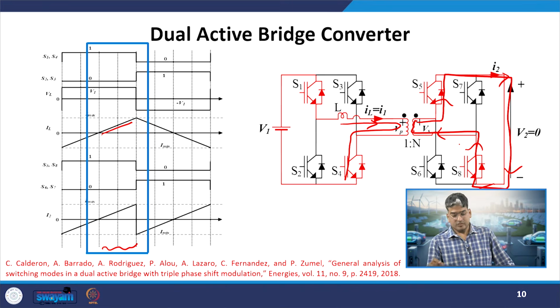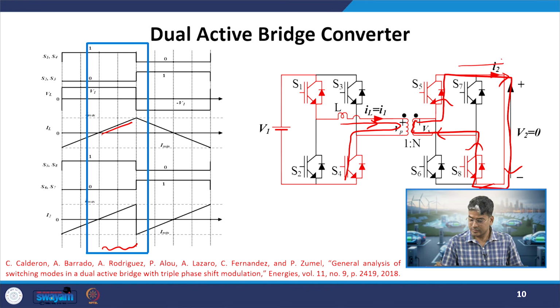Okay. So, now here if I see, the diodes are in the conduction path. Why? In the upward direction over here, the IGBT cannot conduct, so it will be flowing through the diode. Now, if I see the I2 polarity, it is in the direction of our measurement. So, I2 is positive. If you see, I2 has been marked as positive. Okay, got it. So, in the first half cycle, when IL was negative, I2 was also negative. When IL was positive, I2 has been observed to be positive.